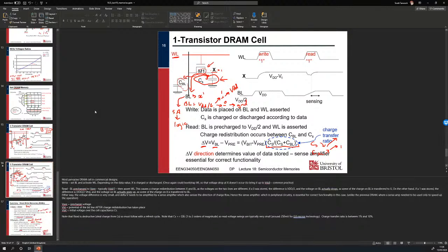So you could normally see this if you have a suitable power monitor on your computer. If you have the tooling to do it, what you would see is that when your processor is completely idle, it'll drop down to a fraction of a watt, while your memory will be consuming more like 4 watts, right? For example, on a desktop computer. Whereas when you've got your system active, you'll see that your processor, both in terms of logic and in terms of its memory, is consuming multiple watts, whereas the DRAM power doesn't really change much.